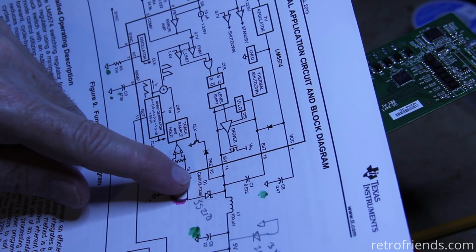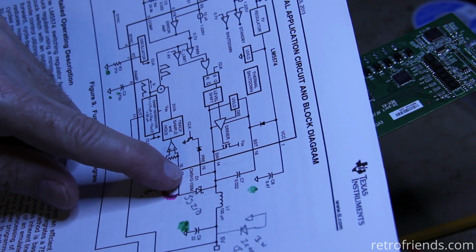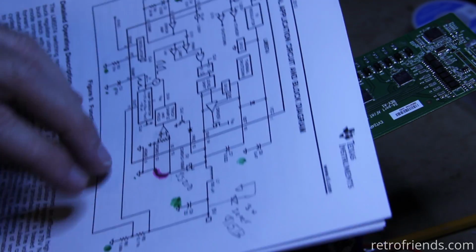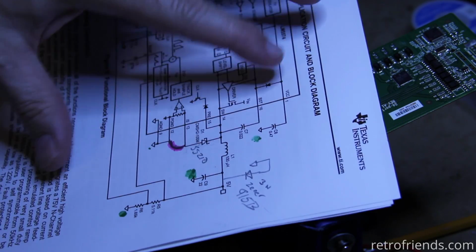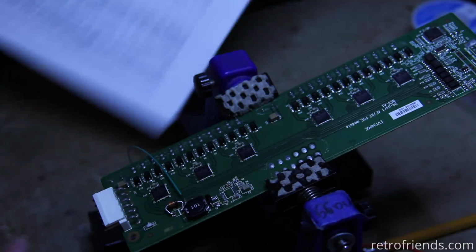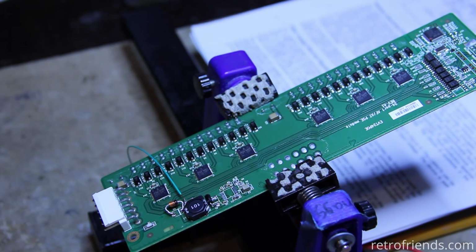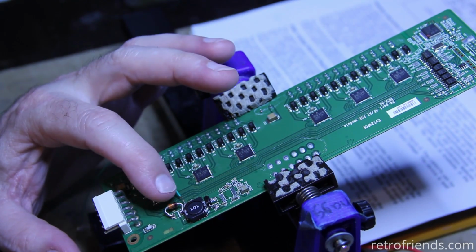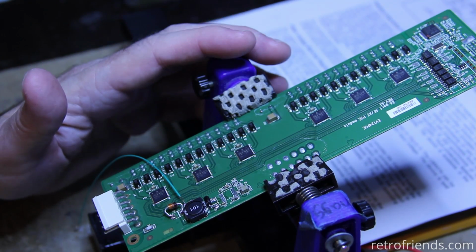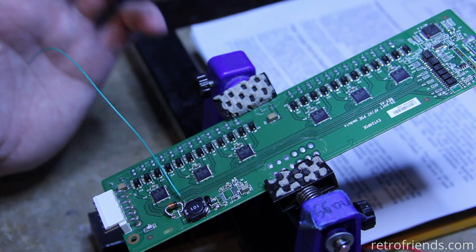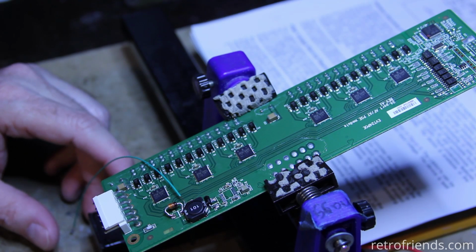They actually tell you exactly which diode it is here, unlike some of the other components. But this sheet does not include this Zener diode in this diagram. It was added for some reason. So anyway, I'm going to go ahead and solder that chip back on here, and we're going to remove this test jumper, and we're going to test it again.